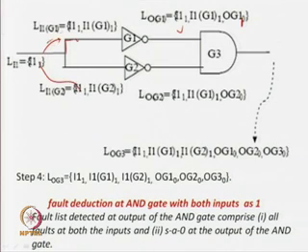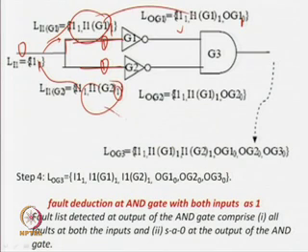So you see this list here and this list here, and you are applying a random pattern of 0 over here. So the pattern applied is a 0 over here, so it detects a stuck-at-1 fault here. Similarly, the signal value is 0 0 over here, because we are applying a 0. So a stuck-at-1 is detected at this net and a stuck-at-1 is detected at this net. And for the inverter, whatever is here and whatever is here, both lists will be here. Now this value is 0 0 here, so it is 1 1 here, so the stuck-at-0 will be detected here, and this stuck-at-0 is detected here.